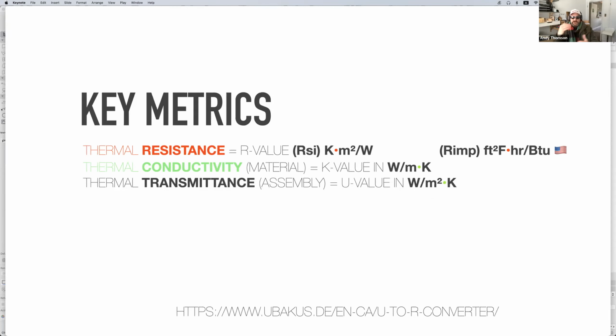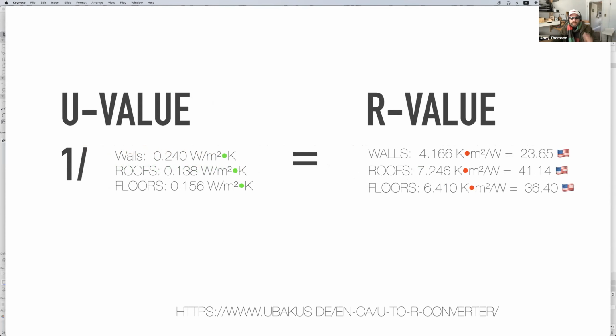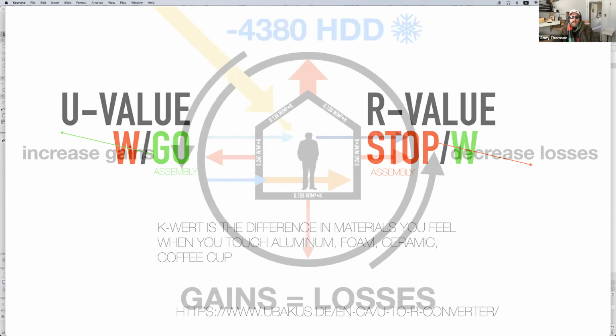And the U value is like the transmission or the power loss through the assembly. That's like the green. It's kind of like a permissive value. And transmittance is similar, so those are green. So again, U value is reciprocal of R value. We're used to R value. So if we're talking about an R23 wall in imperial terms, that's an R4 RSI wall, and so on. So back to this, U value is like transmission, and R value is stopping power of the assembly.